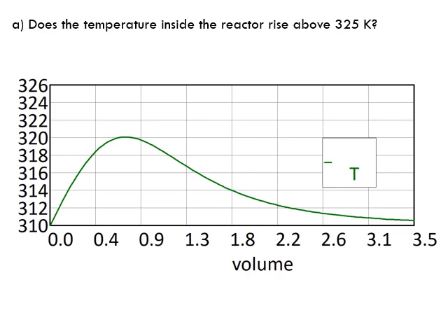And please note that we needed to look at the temperature profile throughout the reactor, not only at the exit, because this is no longer an adiabatic reactor where the highest temperature would be at the exit. No, this is a reactor where we are exchanging heat. So at any location of the reactor, the temperature could be at its highest value.